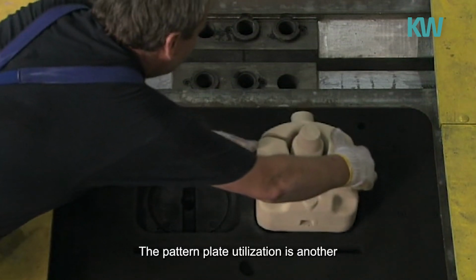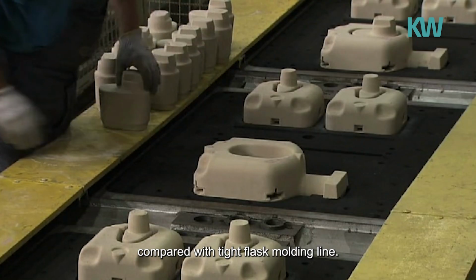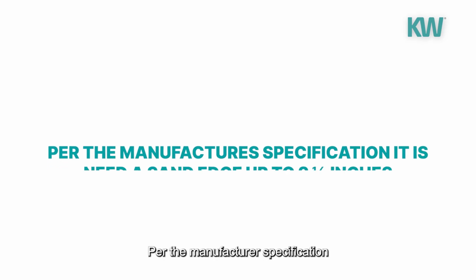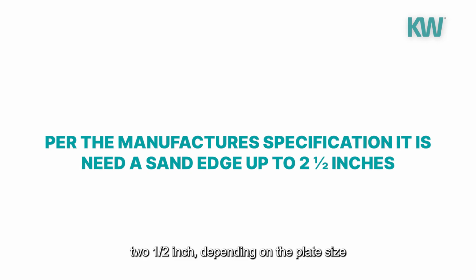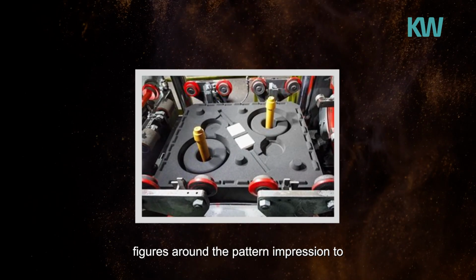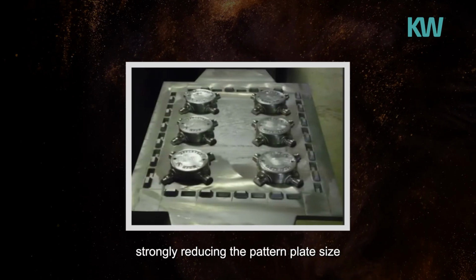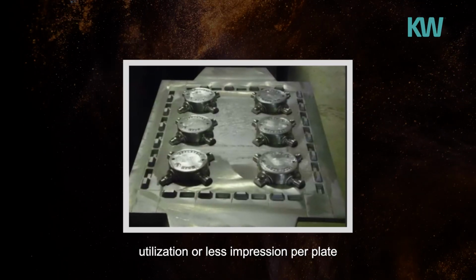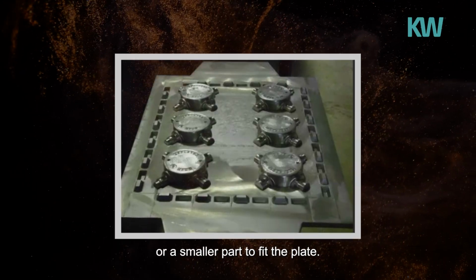The pattern plate utilization is another negative aspect of a match plate molding line compared with tight flask molding line. Per the manufacturer's specification, it is needed a sand edge up to 2½ inch, depending on the plate size and part geometry, and an interlock figures around the pattern impression to prevent metal leakage and mismatch, both strongly reducing the pattern plate size utilization, or less impression per plate or a smaller part to fit the plate.